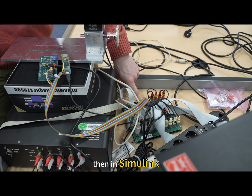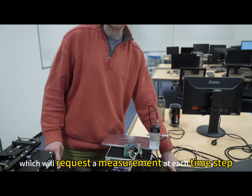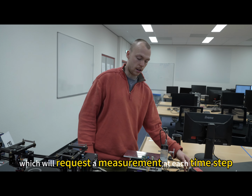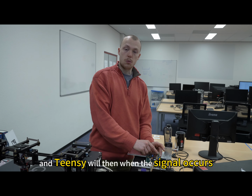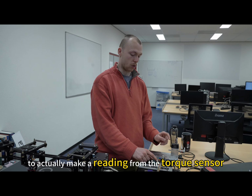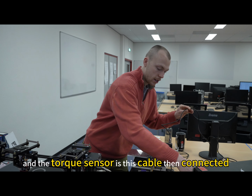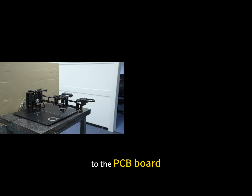Then in Simulink we send a digital pulse signal, which will request a measurement at each time step of the simulation. And Teensy will then, when the signal occurs, send the signal to the PCB to actually make a reading from the torque sensor. And the torque sensor is through this cable then connected to the PCB board.